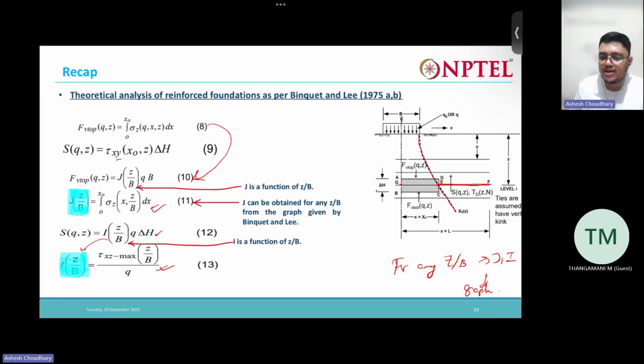If you can recall, in the reinforced earth wall cases, we had a wedge, then we had reinforcement. This length actually provided anchorage into the soil, right? This held the reinforcement in place. If this length is shorter, what will happen? Pull-out failure will occur. The whole failure soil will fall down with the reinforcement. So the length of the reinforcement here is very important.